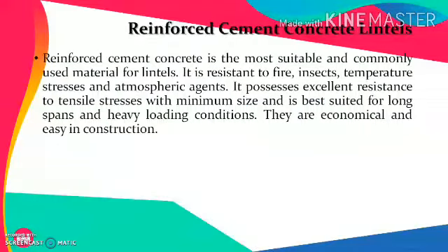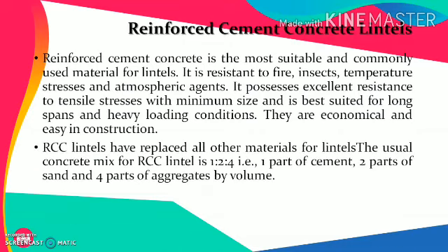RCC lintels. RCC concrete is the most suitable and commonly used material for lintels in most of the buildings. It is resistant to fire, insects, temperature stresses and atmospheric agents. It possesses excellent resistance to tensile stresses with minimum size and is best suited for long spans and heavy loading conditions. They are much economical and easy in construction.